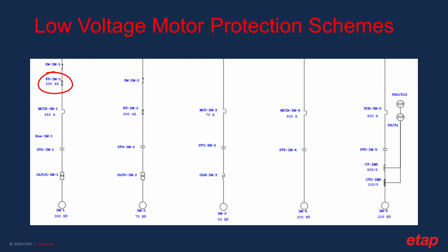If you don't need a breaker in this case, you can replace it with a fuse and then have a switch upstream of the fuse. Naturally, as you know, the difference between these two is the restoration time. For the fuse, if it's blown, you need to replace it. For the breaker, you may switch it on after resolving or removing the fault.